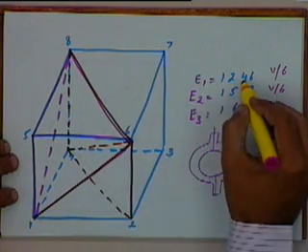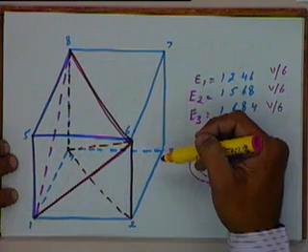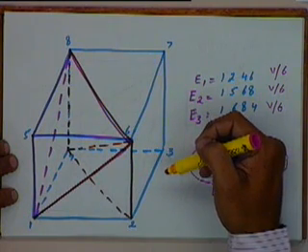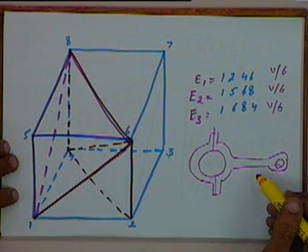And for each tetrahedron we know how to get the local stiffness matrix and the local force matrices, and then we can use it in the global matrices. Any question on this part?